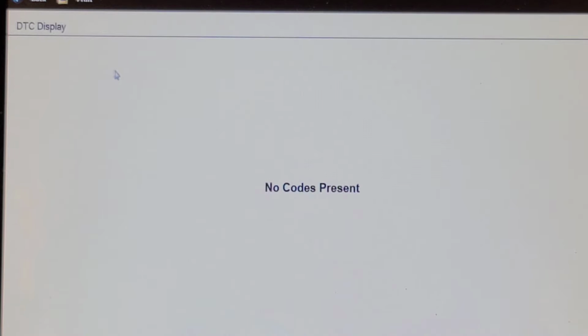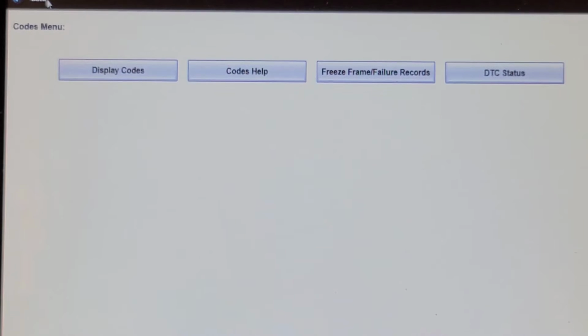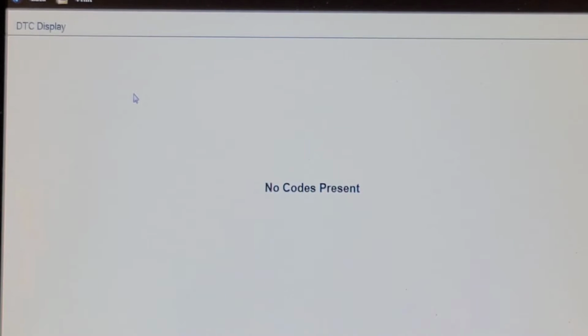So that tells me the wiring's okay, yet the test light did not come on with the scan tool. Now that tells me that the scan tool is malfunctioning, or the bidirectional test is not working correctly. Let's leave this live. I think this is live, and I'm going to unplug that test light. Okay, the test light is unplugged. Okay, maybe this is not a live report.